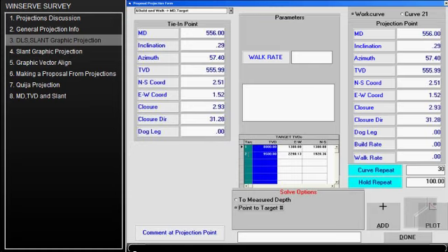Sometimes that has a use in specific instances where you're kicking off and you're pretty much in the opposite direction of the way you want to go, but you've already achieved 4 or 5 degrees of angle, and in the straight section it's just drifted off, and you don't want to lose that angle, you want to maintain that angle as you turn.